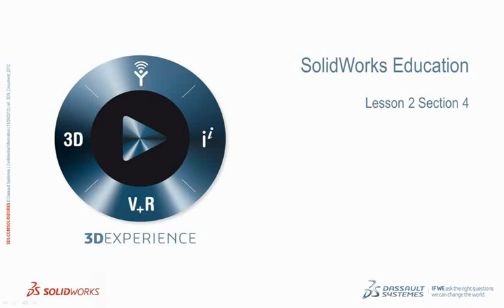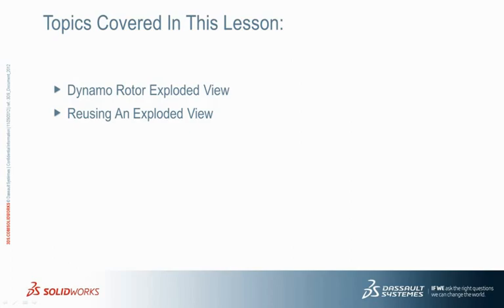Welcome to SOLIDWORKS, the Engineering Design Process, Lesson 2, Section 4. In this section, you'll learn how to create an exploded view of a subassembly, and then reuse that view in a higher level assembly. You'll also add exploded lines to an assembly to indicate and highlight component relationships.